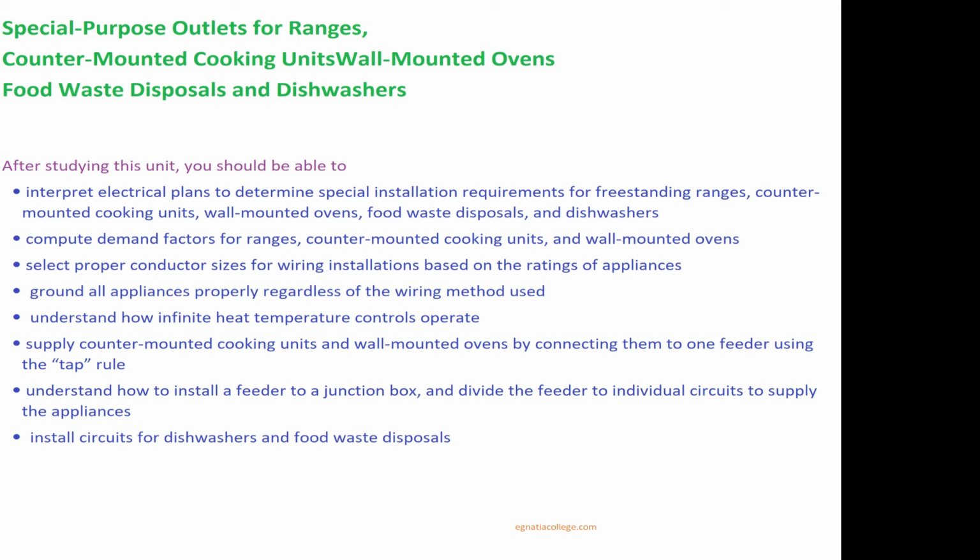Compute demand factors for ranges, counter-mounted cooking units, and wall-mounted ovens. Select proper conductor sizes for wiring installations based on the ratings of appliances. Ground all appliances properly regardless of the wiring method used. Understand how infinite heat temperature controls operate.